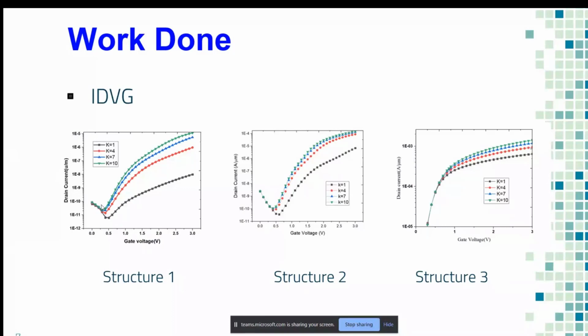After this, the current is very insignificant, as we can see, it's at the bottom. In this state, as we keep increasing the gate voltage, it will reach a certain state where the minority charge carriers diffuse, and the conduction band and the valence band align with each other, and that's when the tunneling happens.